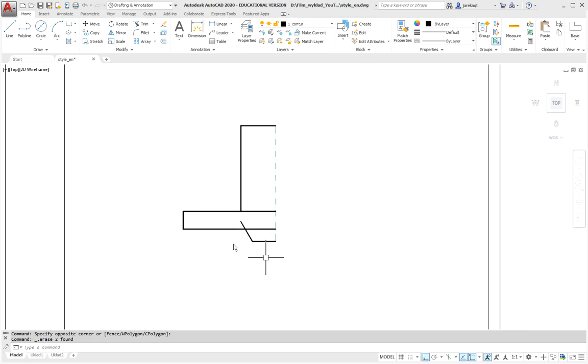It's good to have this outline made to be one polyline, because on the other hand there is the same outline. In connection with this we will indicate objects which will be trimmed, and with enter on, we say what we have to cut, this and that. But these are three independent polylines. It's good to have it as one, i.e. chamfering will connect them together, but at this point we won't be chamfering.